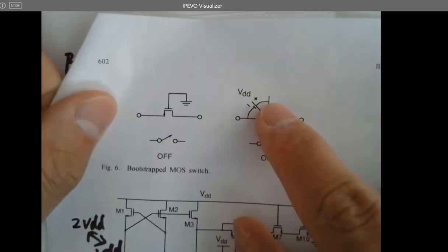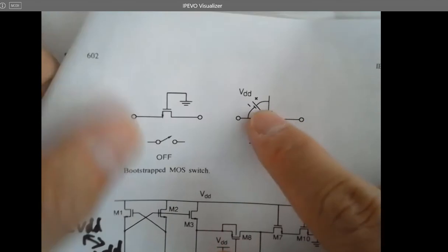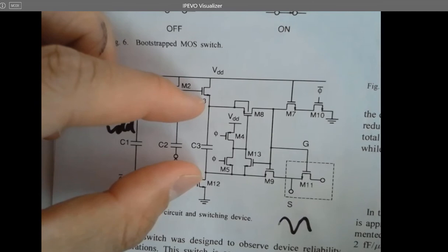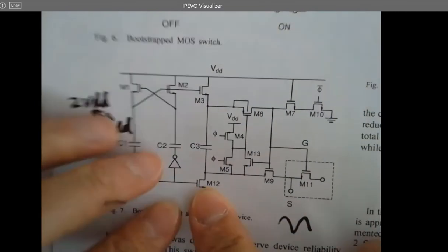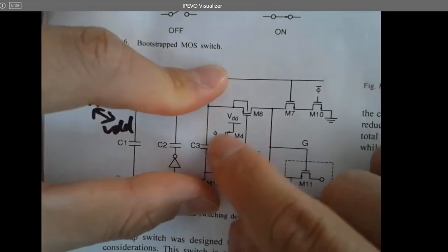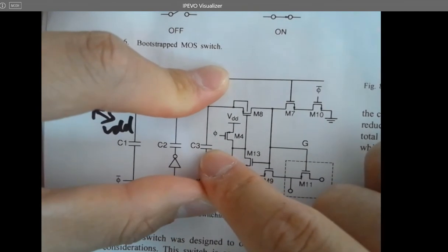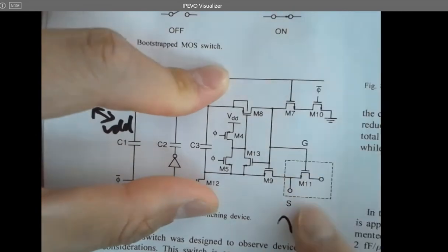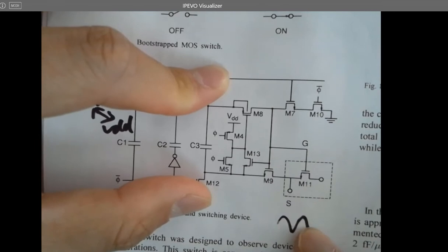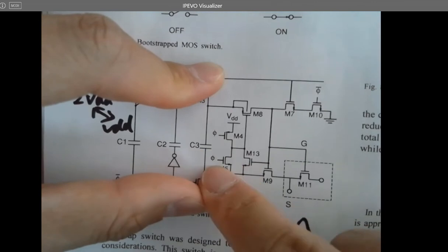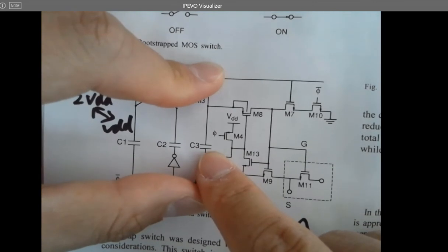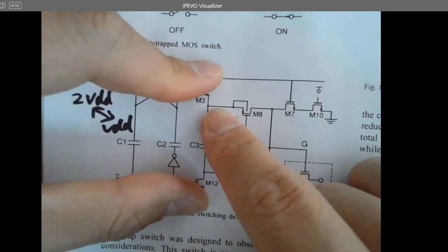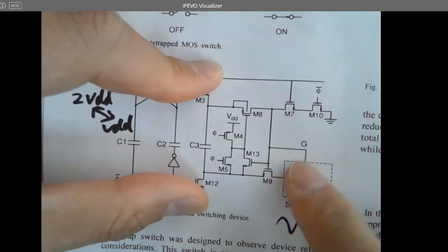All right, the ideal circuit is to tie a voltage source across G and S to make it constant. And now we want to do it this way. The way to do that is we keep a capacitor here to hold the charge. And whenever I turn off this transistor and turn off this transistor as well, you just block it. You can see this C3, capacitor number 3, is serving as a battery over these 2 terminals, here and here. And whenever S is varying, it's going to dump charges or pull charges in or out from the bottom plate of this battery. So it's going to add or subtract the signal's voltage from this voltage point. And this is a pass gate. So whatever is here will be the same as here, which is VG.